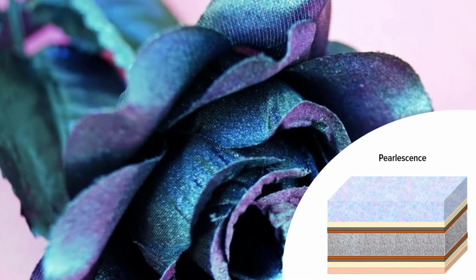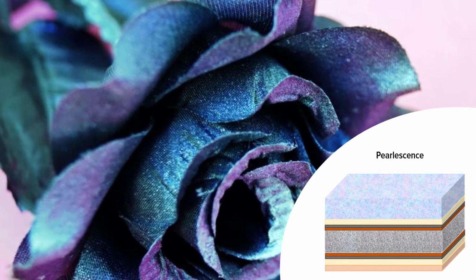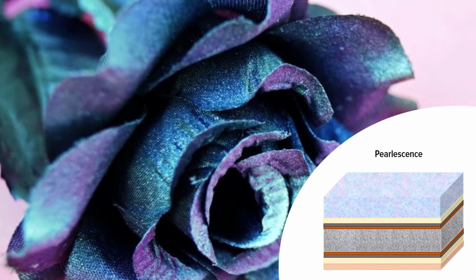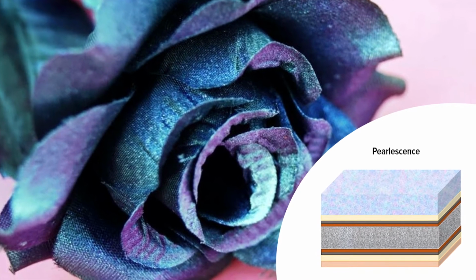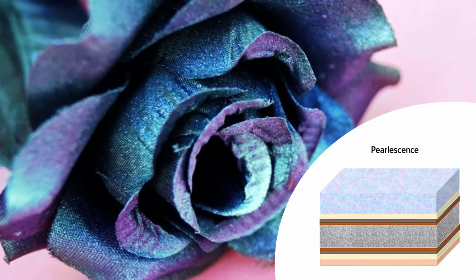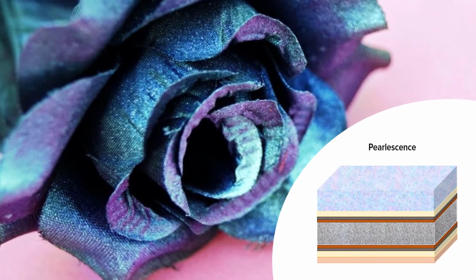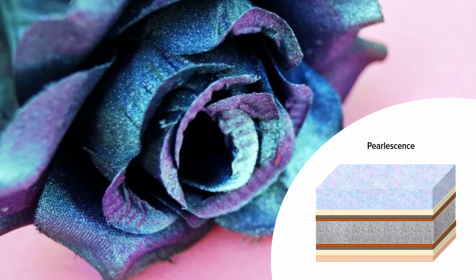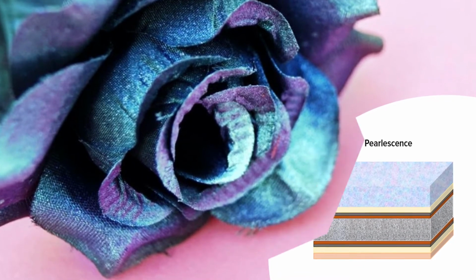Micas can also be used to create colour shifting or pearlescent effects. Pearlescent paints use specially formulated mica pigments that are coated with multiple colours to create an evolving colour aesthetic. Pearlescent paints will create a unique colour and shimmer and produce a different colour from different viewing angles. These produce the same visual impact as micas, but in addition to the depth created by the mica pigment, the colour changes from different viewing angles, adding to the dynamic properties of the finish.